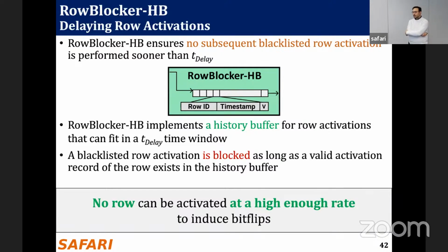Now I understand. Yeah, it's a more area efficient model. Yes, we can use another Bloom filter structure actually. Instead of a counting Bloom filter, we can have just a Bloom filter for the blacklisted rows, right? Then every location pointed to by a hash function is just one bit, instead of, I don't know, a 10-bit counter. So that can work as a good optimization.